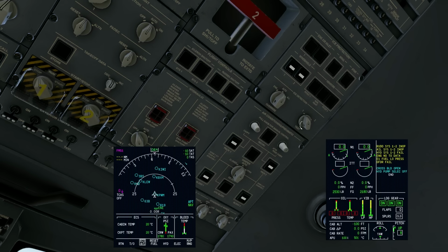We get two messages. We got ice detection 1 fail, and we get an ice condition flashing. So that's that ice condition. That's basically, we've tricked the sensor into firing. There's the ice condition. And it's telling us ice detection 1 fail. Why? Because we're sending a test signal and overriding its own logic, so it doesn't like that. We do the same on number 2.